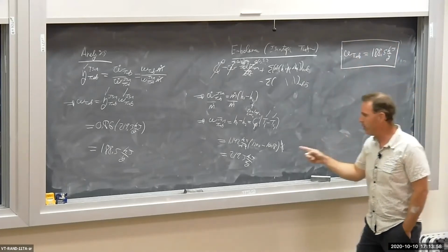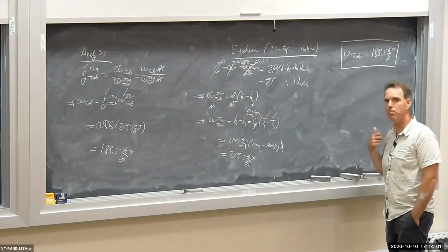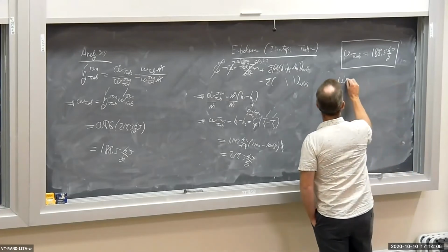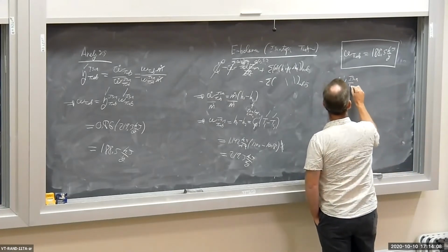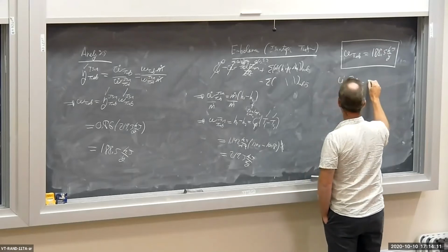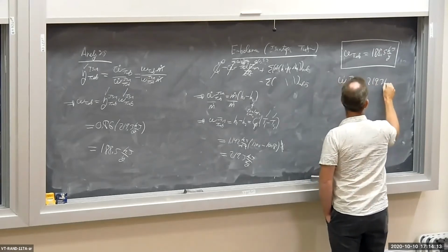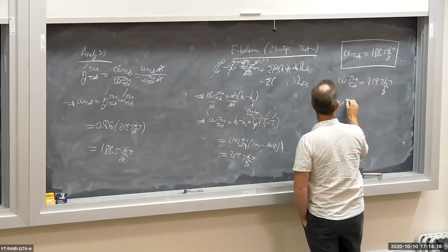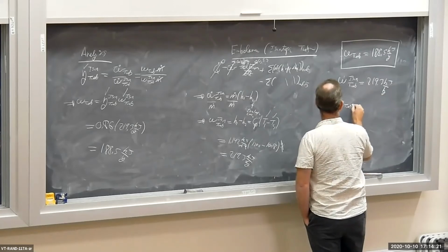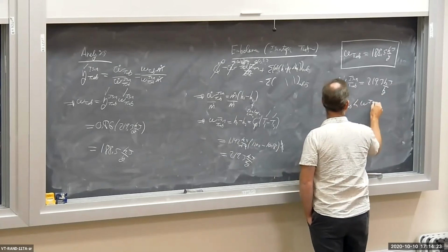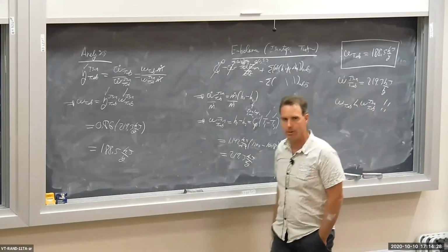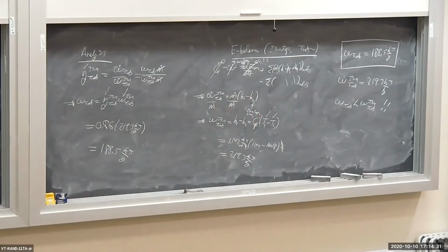Note, the reversible device, the one that produces the maximum possible work between the same pressure limits, W isen turbine, is 219.3 kilojoules per kilogram. So W turbine is less than the isentropic turbine work. The real turbine produces less power than the isentropic turbine.